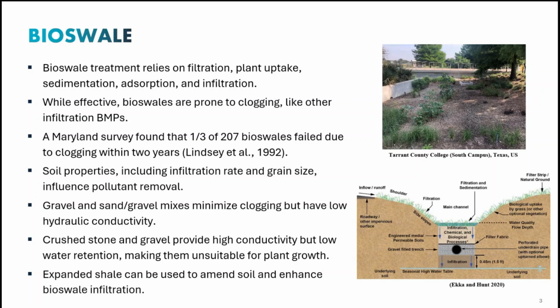The idea in this project was to use, instead of the sand and gravel or crushed stone, expanded shale. Expanded shale is a new material that's been used in different industries. So we thought that would be the opportunity to test the expanded shale in the design of bioswales. Next slide, please.